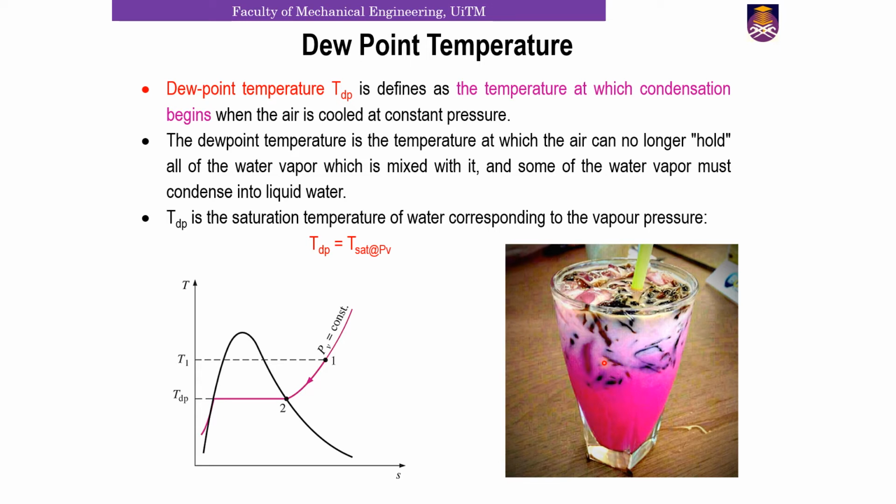So you will see that we have this dew formation on grass early in the morning, and this is formed because of the dew point temperature. In summer, a considerable amount of water vaporizes during the day, just like what happens in Malaysia. As the temperature falls during the night, so does the moisture capacity of the air. This moisture capacity is the maximum amount of moisture the air can hold. After a while, the moisture capacity of the air equals its moisture content. At this point, your air is saturated and its relative humidity is almost 100%. Any drop in temperature will result in condensation of some of this moisture, and this is the beginning of the dew formation that you see on the grass.